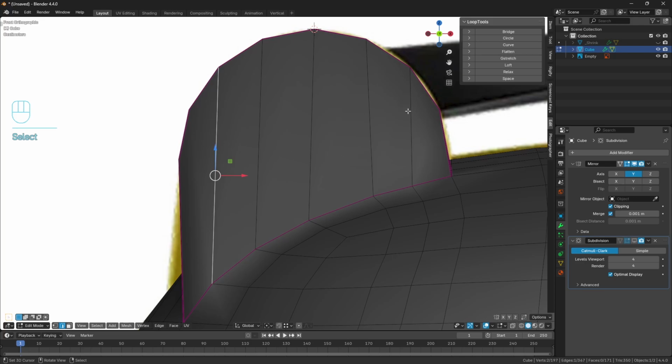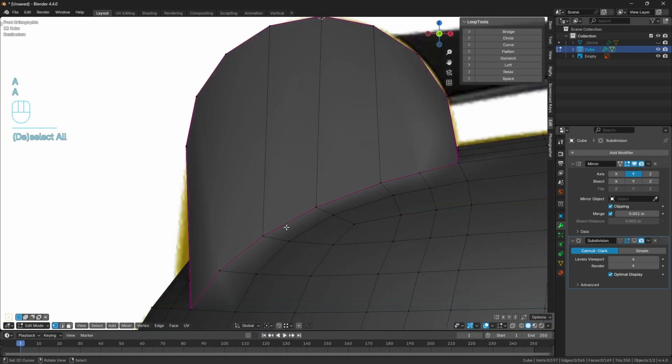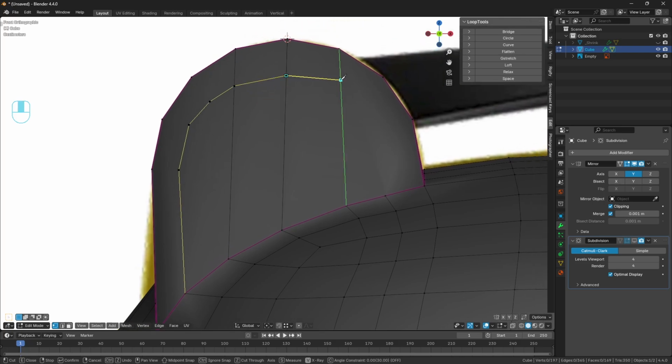So let's just go ahead, I'm going to select this edge and this edge here and Control X to dissolve them. And then I'll do this in vertex select mode, it'll make it a little bit easier to see. I'm going to use K for the knife tool, and I'm just going to click down here, and then I can see a vertex here, so I'm just going to bring this up, click roughly in line with that vertex, see another one here, so I'll click around there, another one here, somewhere there. This one I'll click onto the edge, and same as that one there, as well as that one. Another vertex there, so I'll click roughly around there, another one here, and then I'll click back down at this vertex here.